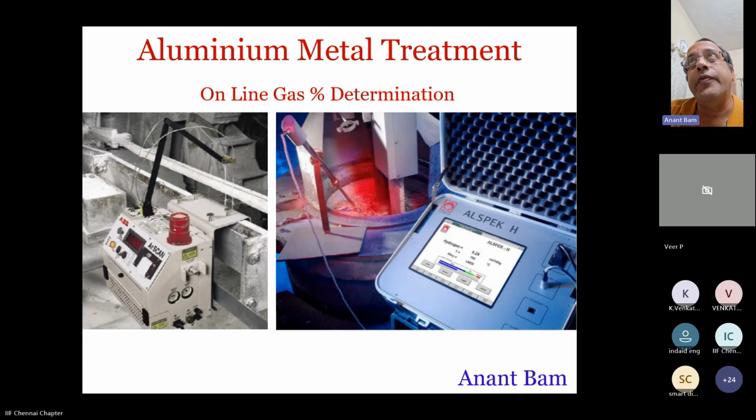But density index analyzer along with reduced pressure apparatus is available at price range between 3 to 7 lakh rupees. Some of the fancy equipment like Ideco or others are further expensive. They are European made, but there are Indian makers who make these machines, and 3 to 5 lakh rupees is the price range. And they are quite effective, quite quick. So you find a lot of population of density index analyzers in Indian foundries.